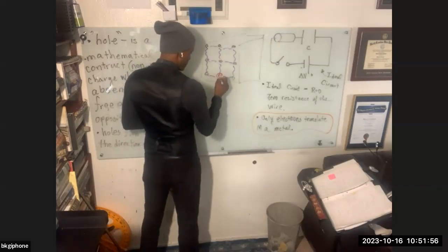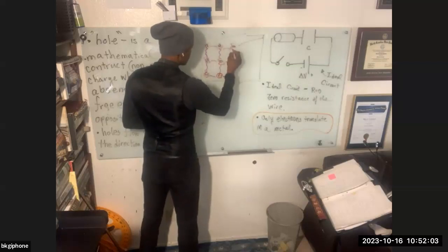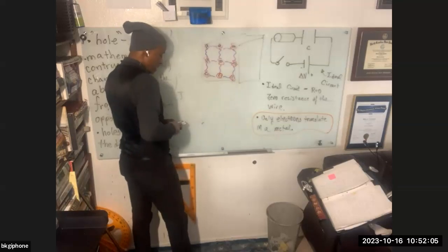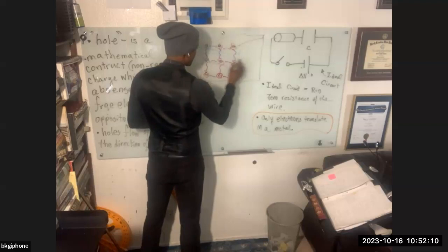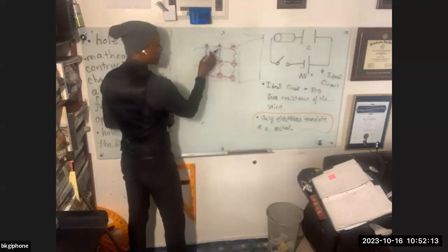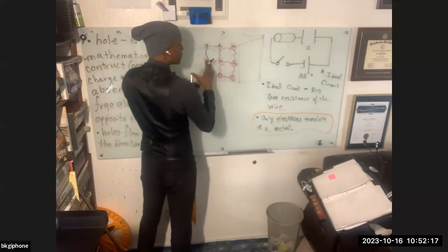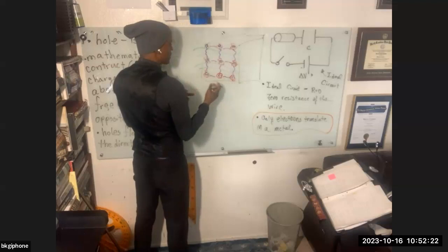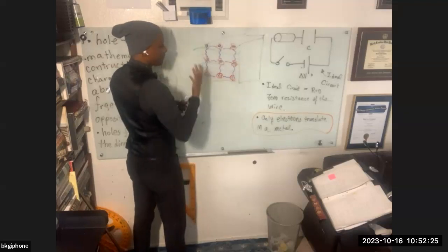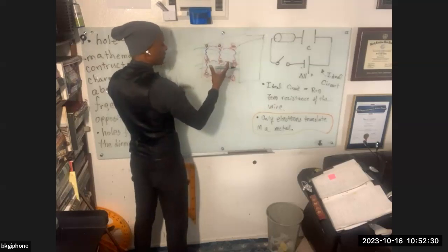And so these are the bound electrons around that, like the electron cloud. And then we have the Fermi electrons. Now I drew them like this, kind of implying that they're flowing through, but they're not flowing. They're just electrons that are just there, and they have their own average vibration, and as I said, the average value is not moving, but I don't know a way to draw that. And also because I refer to it as a Fermi C, and C implies current, which we will have current if we have a voltage on it. But in general, there's no current, they're just there.